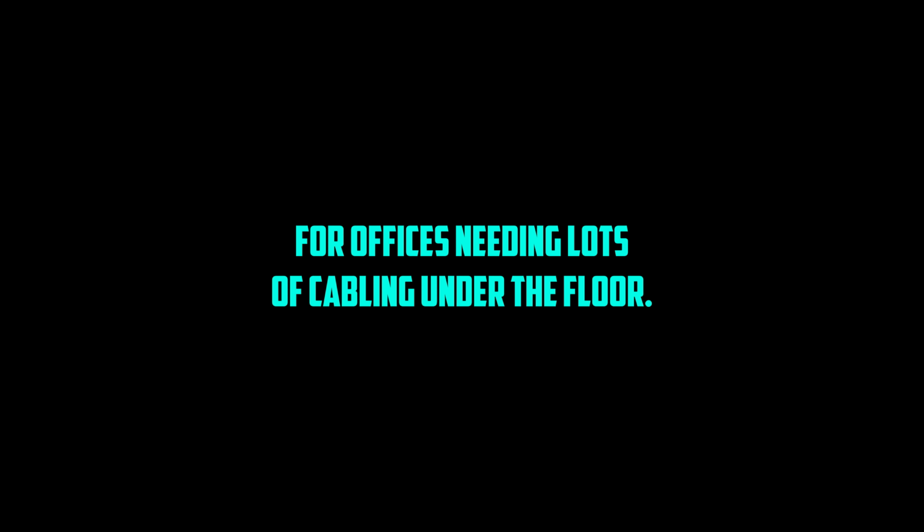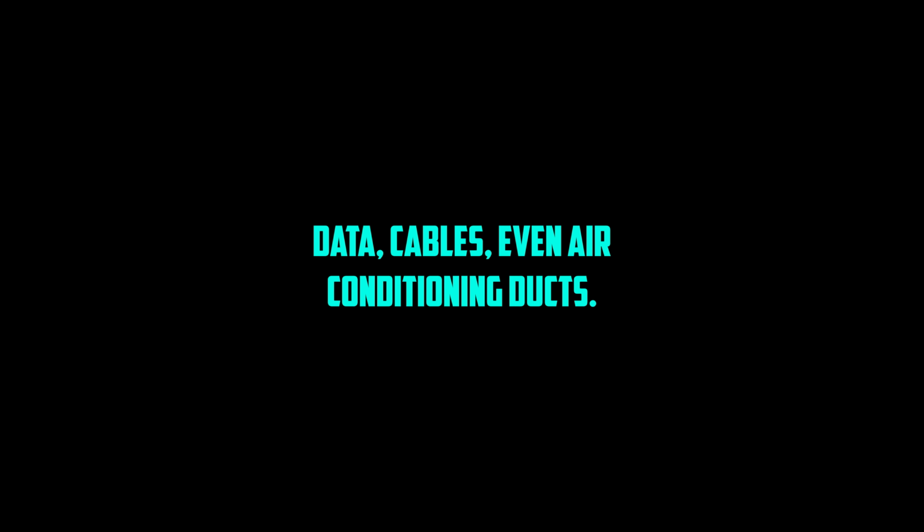Finally, for structures, raised flooring came about because of computers, right? Pretty much. Developed mainly in the 70s for offices needing lots of cabling under the floor. It's basically floor panels, often 600 millimeters square, sitting on adjustable pedestals, creates a void underneath for wires, data cables, even air conditioning ducts. Pedestal heights vary enormously, from just 30 millimeters up to 600 millimeters or more.